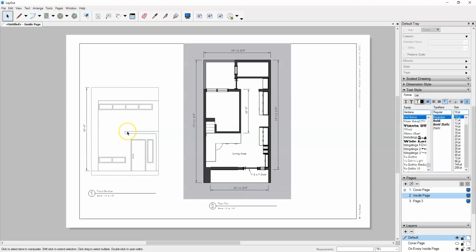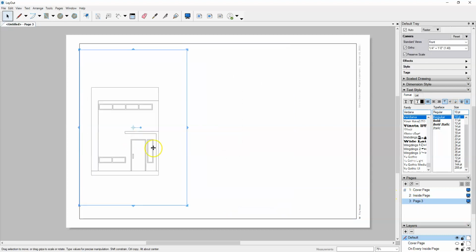Okay. Yeah. So the weird thing about layout is there is no Add Viewport button. So I can't just open a new layout file and add a new viewport. You have to actually export your model to layout in order to get that viewport, and then just copy and paste viewports around. It's very strange. But yeah, you can just Control C for copy, go to your next page, Control V for paste, and then from there you can do the same thing, assign a different scene, so on and so forth. Thank you.